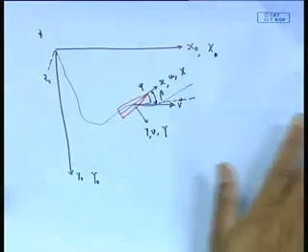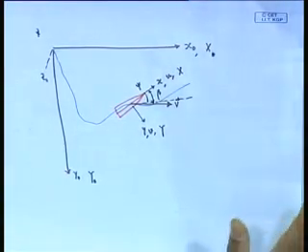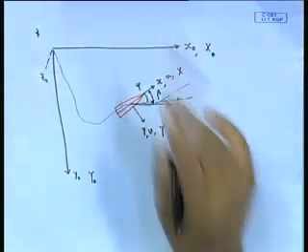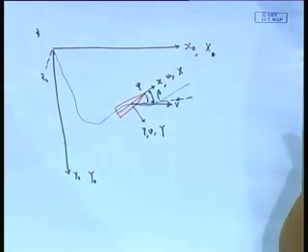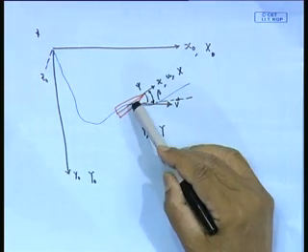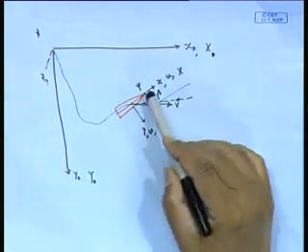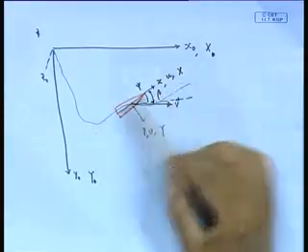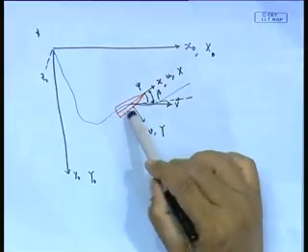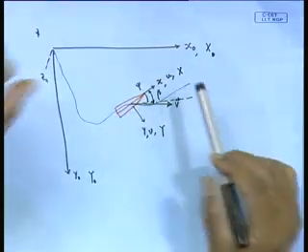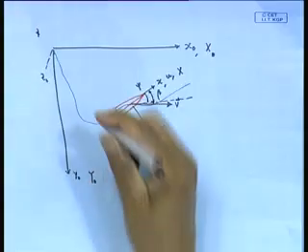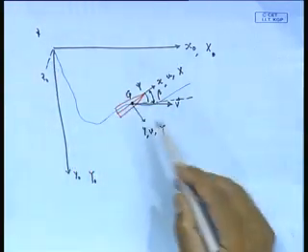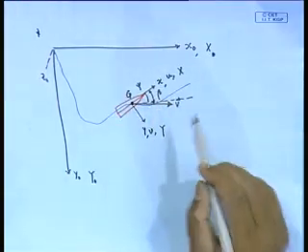Okay, this is just quickly a recap of what we have done. We are discussing now the subject of a ship maneuvering in a horizontal plane, and I mentioned in the last class during the introduction that the way it will behave depends purely on the hydrodynamic forces that get created on the body because of the flow past it, because it is not moving with zero angle of attack. Here, this blue line is the trace of its center of gravity, some point we are taking as CG, and the orientation is given by this beta and psi angle.